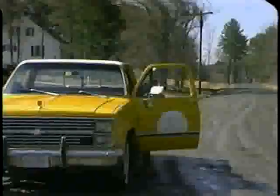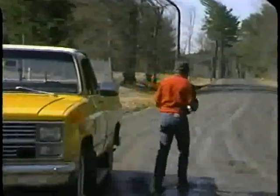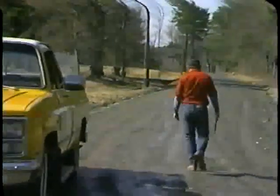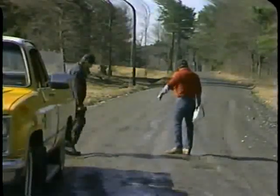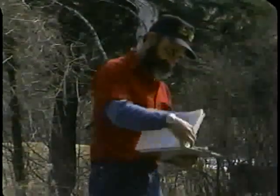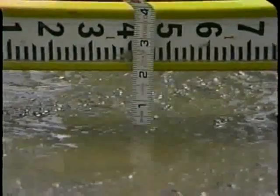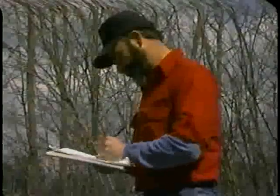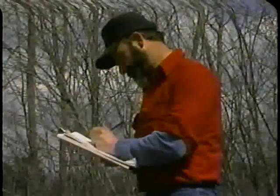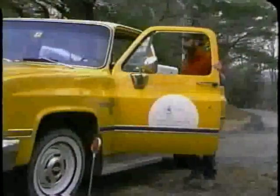You'll no doubt run into situations where it'll be difficult to tell which distress is which, or several may occur together. A sample with improper cross-section may also have potholes and ruts. In this situation, use your best judgment. Decide which is which, and then measure each distress separately. The system is flexible enough to give an accurate rating under most circumstances. With experience, spotting the different problems will become much easier.